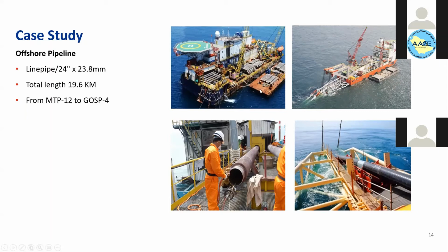So the material is brought using a material barge from onshore and loaded onto this vessel. The barge crew will handle the material to the welding floor. They will weld the joints, then they will start laying the pipe on the sea bed. So we need to calculate the cost of all this activity, including the material and the construction. And the construction here involves two things: the installation of the pipe and the fabrication. So let's go over them one by one.